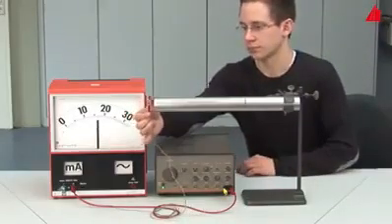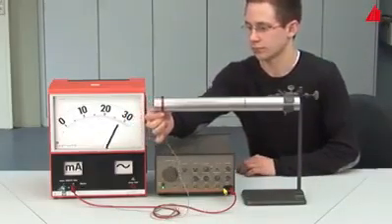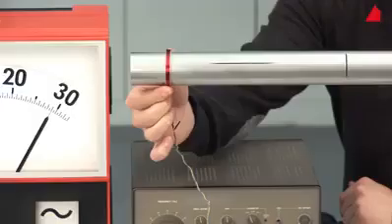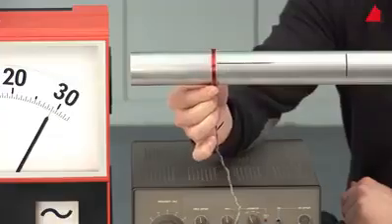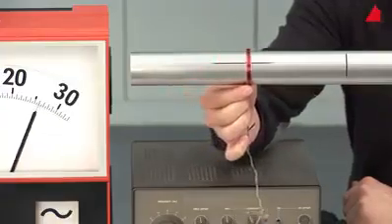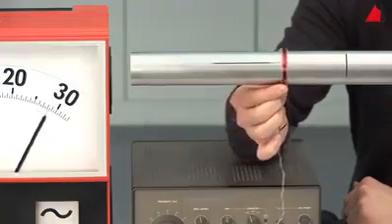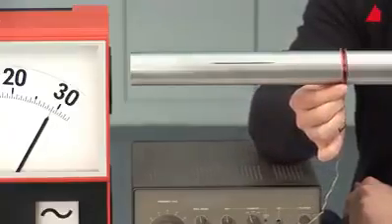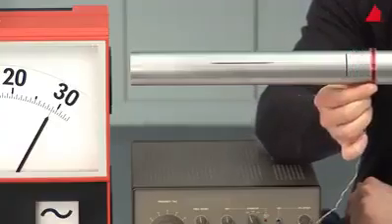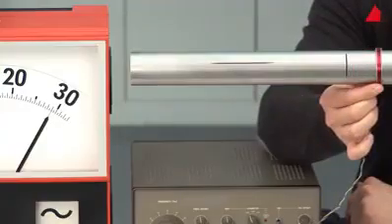The current consumption of the coil is still relatively low. Once the coil is positioned over the intact part of the tube, the magnitude of the current is high. The current decreases in the region of the longitudinal cut and reaches the original magnitude again in the intact part of the tube. The cut in circumferential direction has apparently no influence on the current.